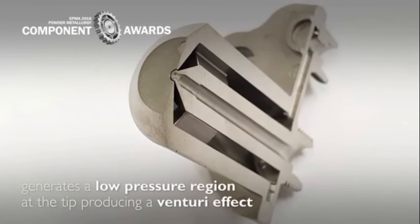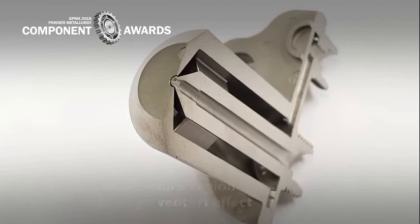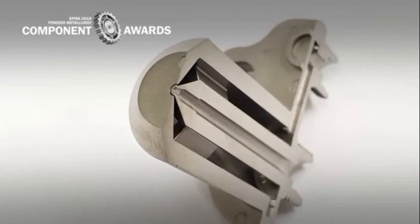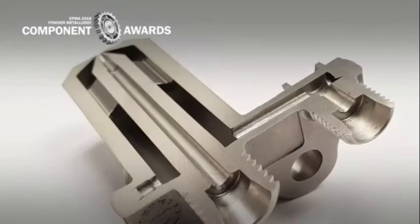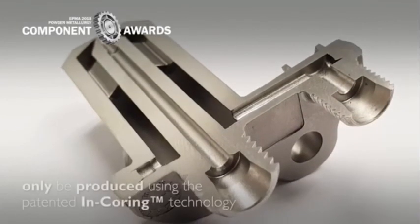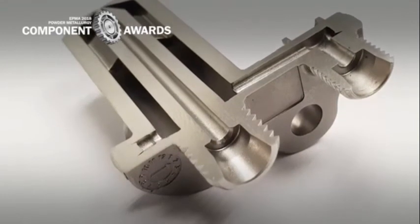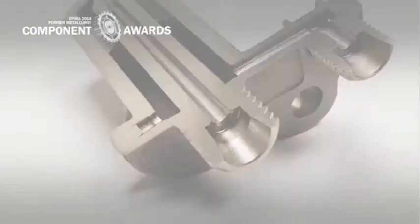This generates a low-pressure region at the tip, producing a Venturi effect, which draws out the urea from the middle channel and sprays it onto the SCR system, which will reduce the exhaust nitrogen oxide to nitrogen gas and water. The special feature is the undercut internal channel, which can only be produced using our patented in-coring technology. No other metal forming process can produce this near-net shape with minimal secondary finishing operations, making